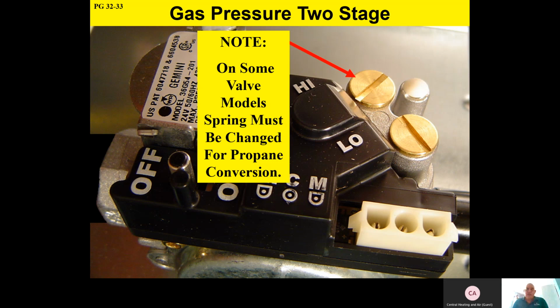And if you look at the chemistry of propane, you'll see that that's why it's going to have more water content when it burns, more steam in the combustion process. And so most of our contractors find that stainless steel burners last a lot longer and work better. So we recommend that if you do a propane conversion, go ahead and plan on using stainless steel burners because they are optimized for propane operation.